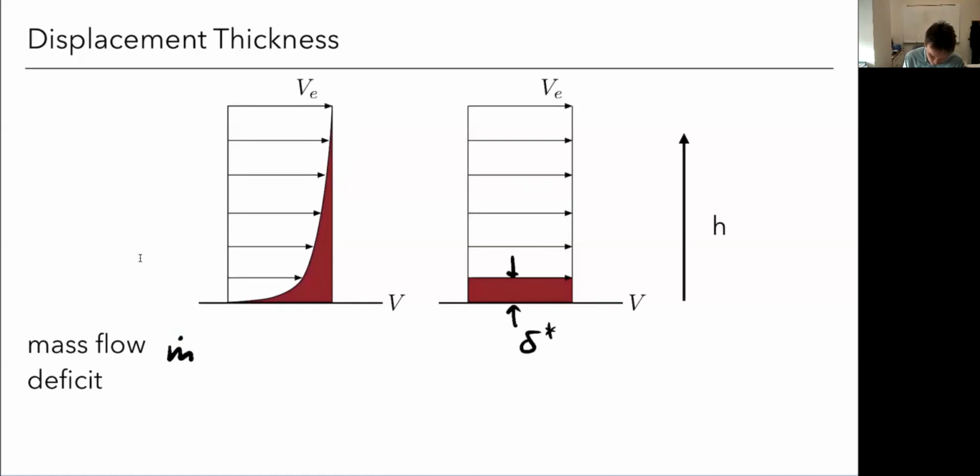And it's going to just be rho VA, right? So rho U dy in this case. That's my mass flow rate. And I just have to integrate that in a general way. On the case on the right, I could write it this way just for convenience. It's equal to an integral, but it's an easy integral, right? Because everything's constant, but I'm going to keep it as an integral for now because it just makes things easier for the derivation. Rho edge V edge dy, right?